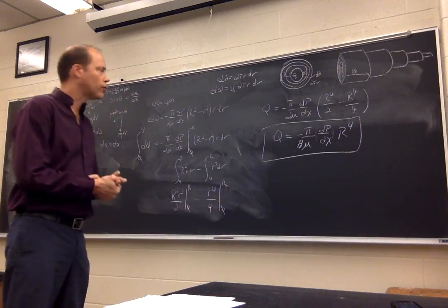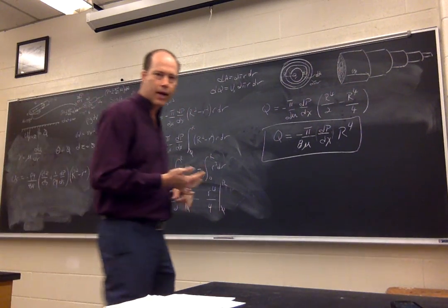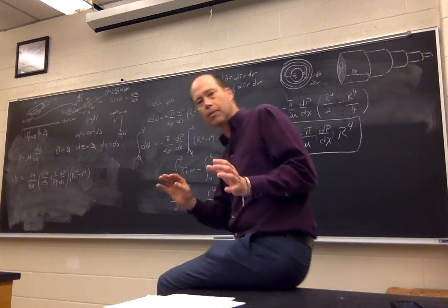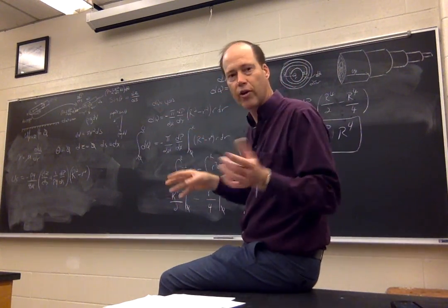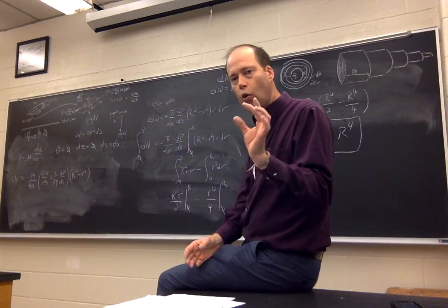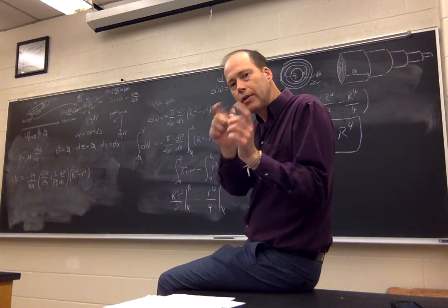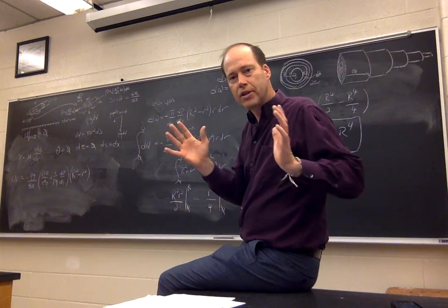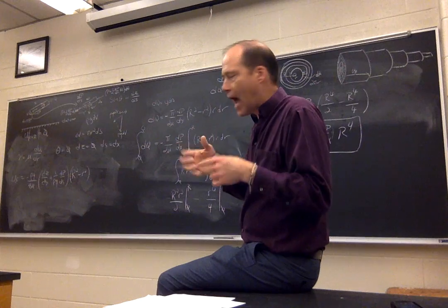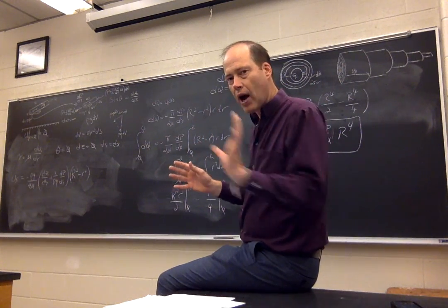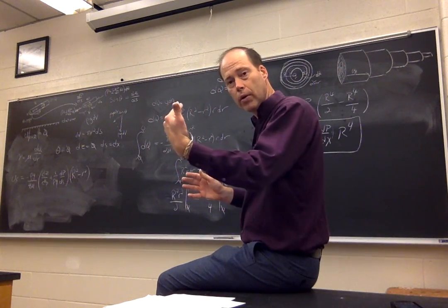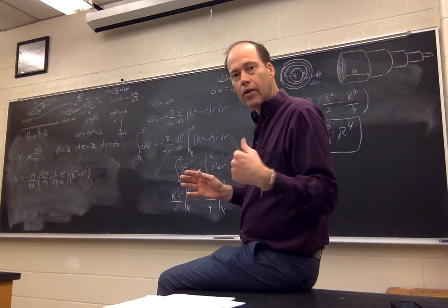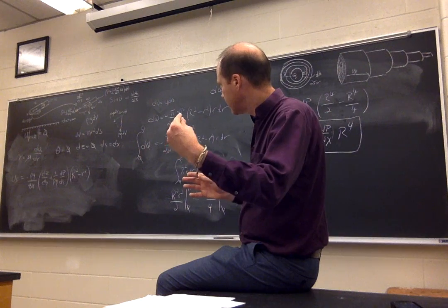We got to this through a few things. One is we drew our problem like we always do. We assess the geometry of that problem. Once we assess the geometry, then we look at a control piece of that and assess all the little changes that are happening on it. Then we assess the forces acting on that control piece, and we sum up all the driving forces that are moving the water forward, which are related to pressure and change in elevation.